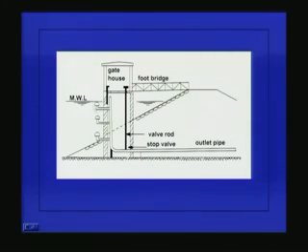And then there is a strainer, and all the fine material and debris is not allowed to enter into this pipe, but the ports are at different levels. Water enters into this pipe, the riser, and then directly flows through this outlet pipe. So that way there is no water which is stored in this intake structure at all.